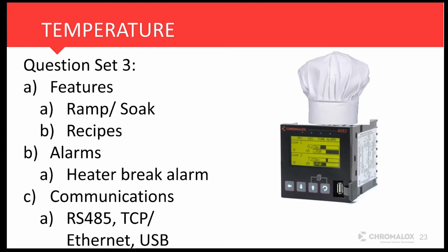So after you go through these 3 question sets, your possible choices as far as controllers that you even can use should be very small. And my rule of thumb is to choose the simplest one that hits all of the features needed. So in my opinion, 2 20 series or even 2 40 series controllers, let's say you wanted to control 2 loops, using 2 of those simple controllers will actually be less expensive and way less complicated than using a 4082.